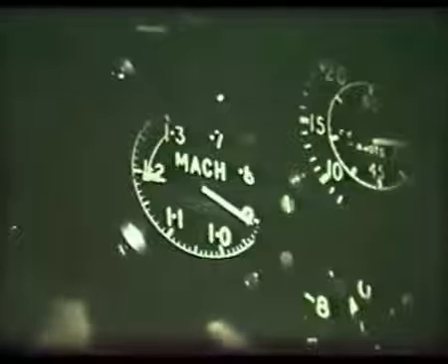As it's approaching the speed of sound, the most important result of the shock wave is to cause the airflow to separate from the wing's surface. This is called shock-induced separation. It produces a large turbulent wake which alters the pressure distribution, lift is reduced, and the turbulence creates drag. The tufts lie flush when the airflow is smooth, and flap when shock-induced separation occurs.